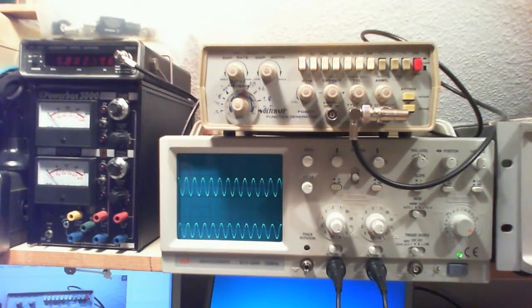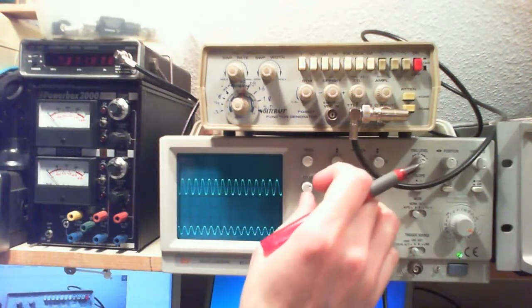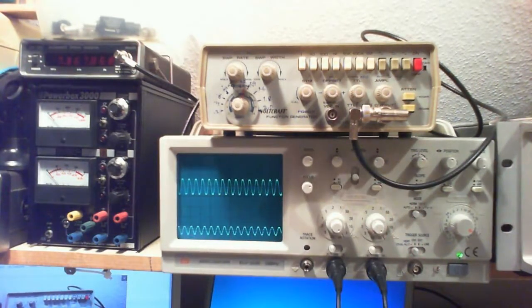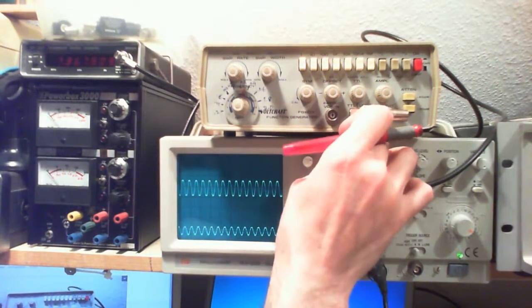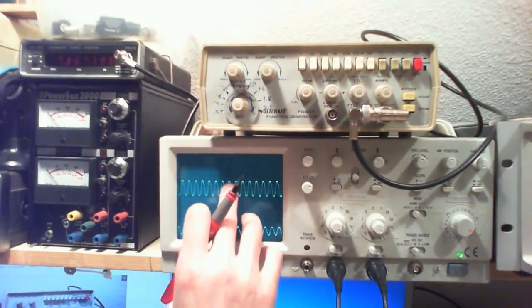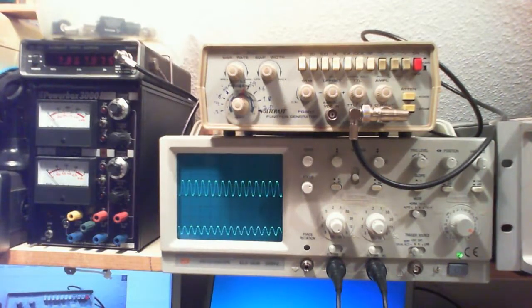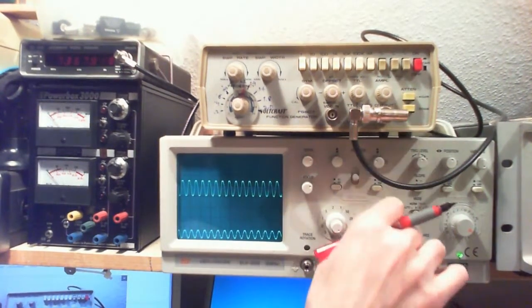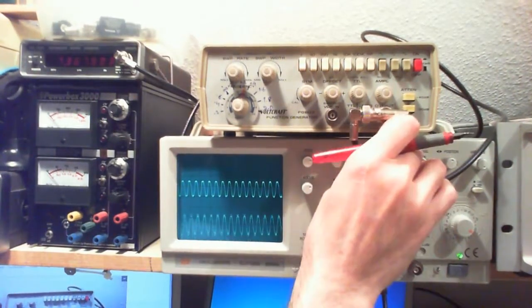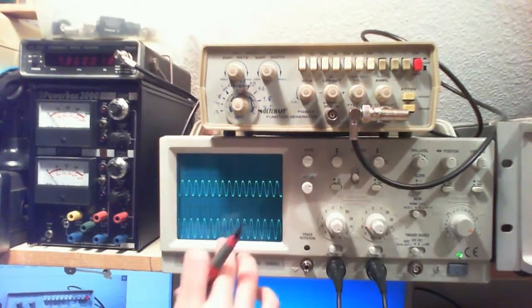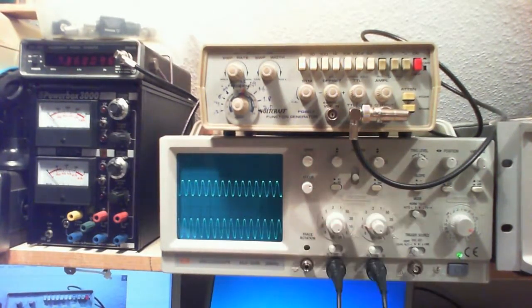And then if I keep increasing the frequency, you see the output is actually decreasing, meaning that at 7.4 megahertz or so, my input is at about 1.5 times 10, so 15 volts peak to peak. My output is at about 1.9 times 2, which is 3.8 volts.